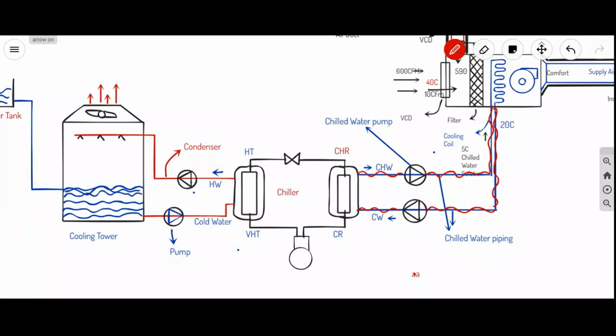Here we connect an expansion tank. Why this expansion tank? Because when the water works at different temperatures, it contracts and expands. That may create some problem in the piping, such as a leak or a breakage near the pump. So we connect an expansion water tank to this AC, and when the water level drops, we add makeup water from the expansion tank.